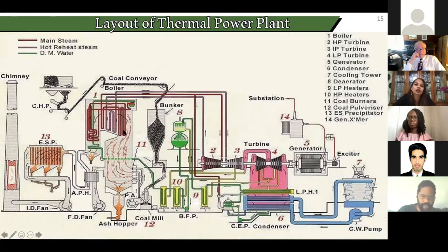In that process, it heats the water. So the air and flue gas cycle and the water cycle are in one furnace. When it heats the water and steam, and it gets the temperature and pressure that we need in a 1,000 megawatt power plant, then it rotates the turbine, the generator and the exciter on the same shaft, which causes it to rotate at 3,000 rpm.